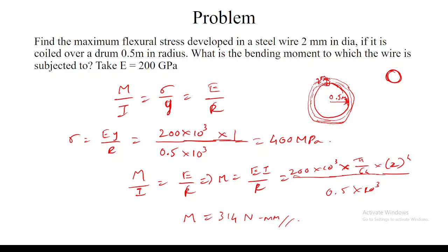So up to this it is clear, right? What all we have seen in today's class: we have seen only the bending stress in beams. And if they are asking, for example, in a shear force diagram problem, they can also ask what will be the bending stress at any cross section. During that problem, you have to find out what is the bending moment at that particular cross section, and then you have to use this M by c formula to get the bending stress value.